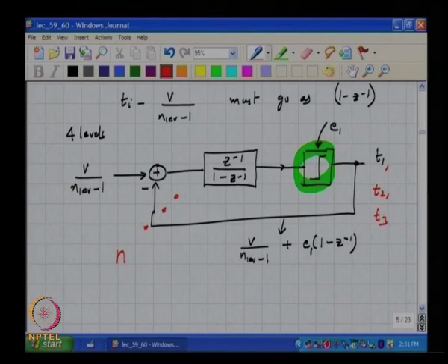You understand? And what is that? If you have a 2 level sequence, what is it becoming? What is the equivalent? It is becoming a 2 level DAC, it is becoming a single bit DAC, right, which we know by definition is insensitive to mismatch. Okay, but what is the problem? No, don't jump ahead.